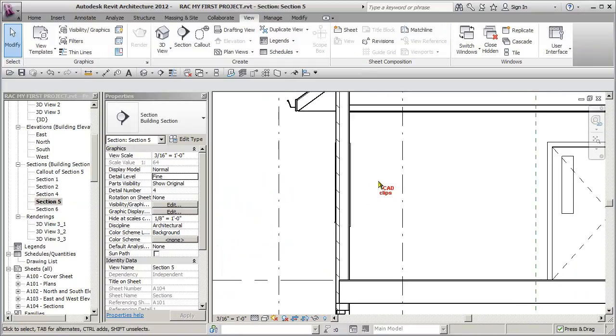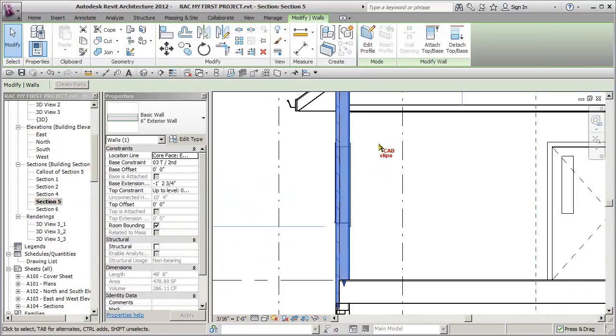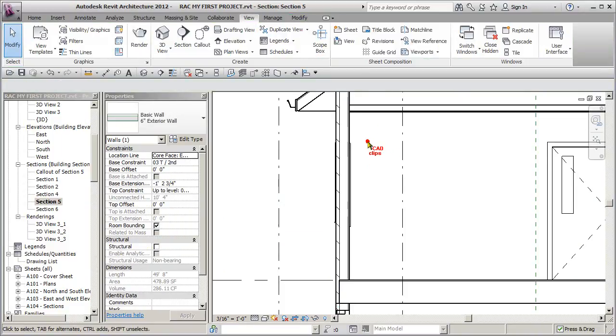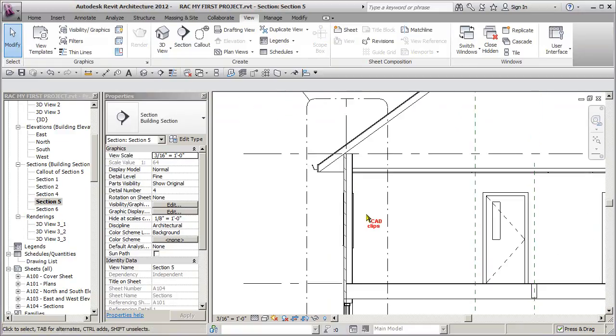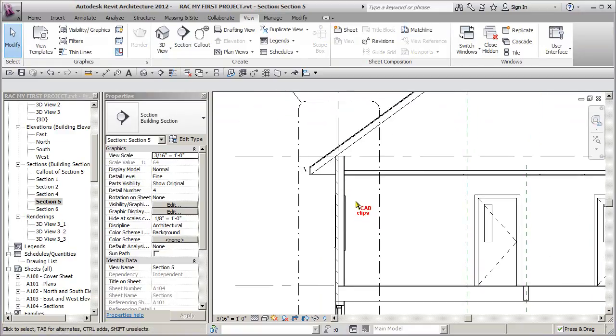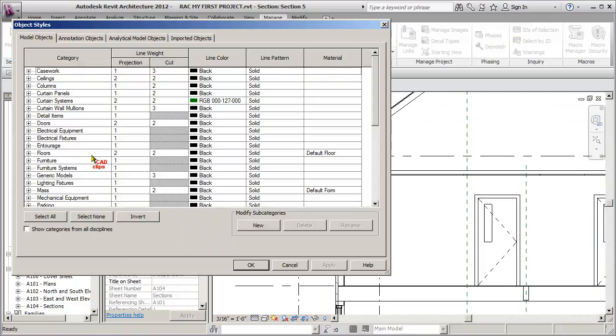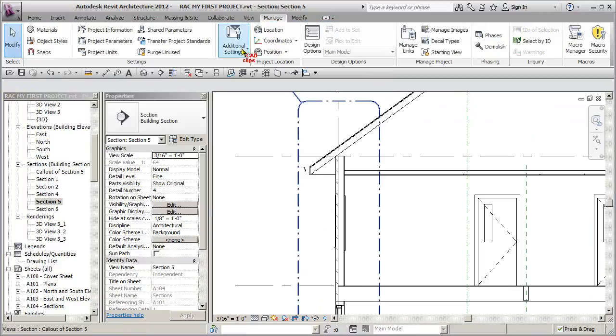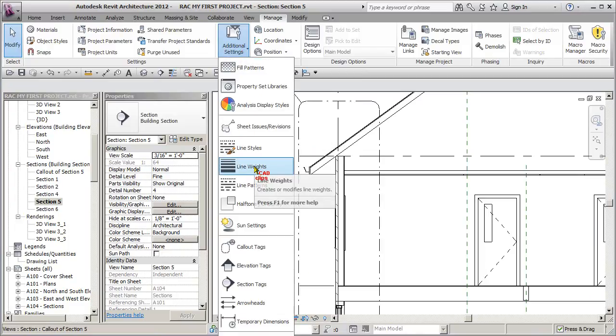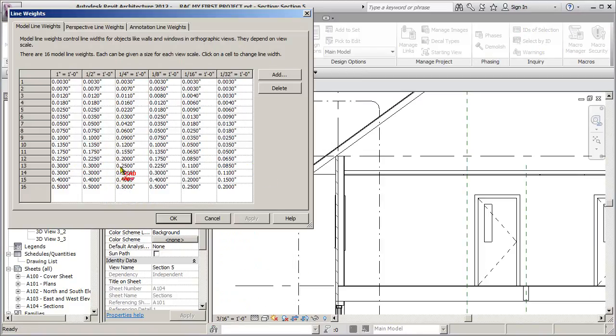Okay, so there is some even more detail overrides you can do by clicking on here per view as far as line weights go. Okay, your overall line weights, when we keep picking our line weights and setting them to be pen 1 and pen 2 and pen 3 in our object styles, okay, these numbers can be further refined by going into here and actually going into these pen weights, and this is the table.